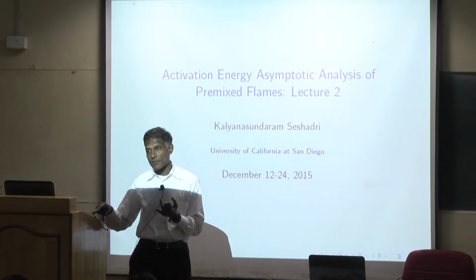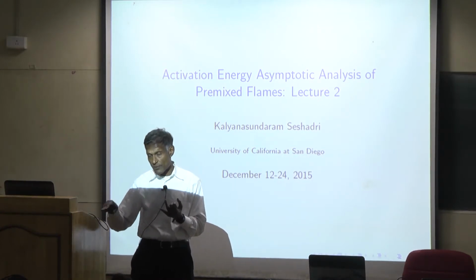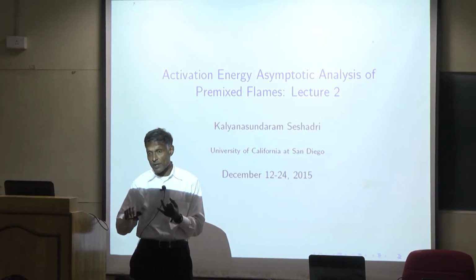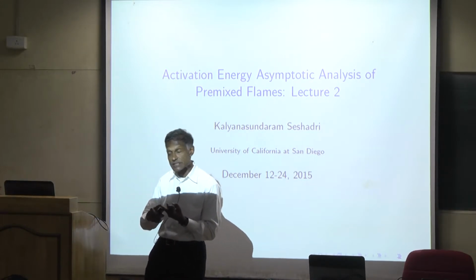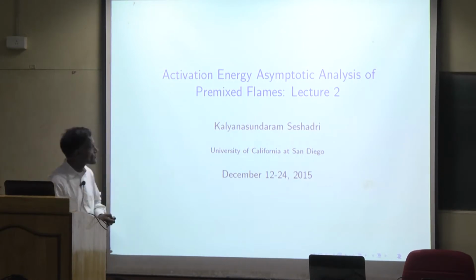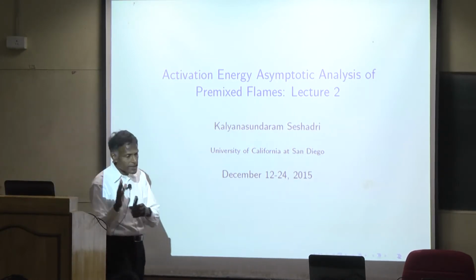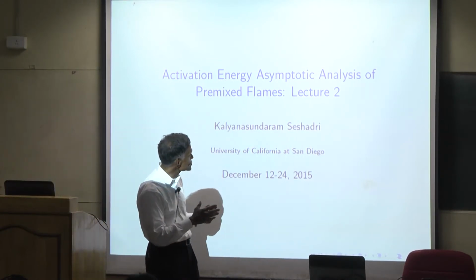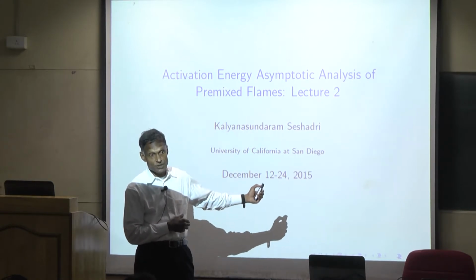A small Damkohler number is where the system has low reaction. And to get ignition and extinction phenomena, you must have large activation energy and large Damkohler numbers. So those are the key points which I wanted to make. I'm going to use all those ideas which we have developed so far to analyze problems in combustion.